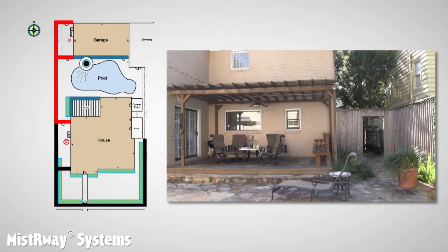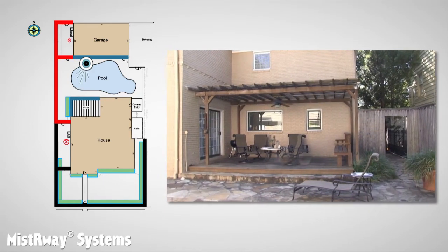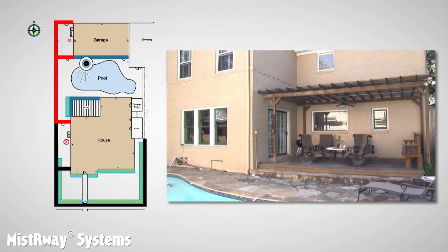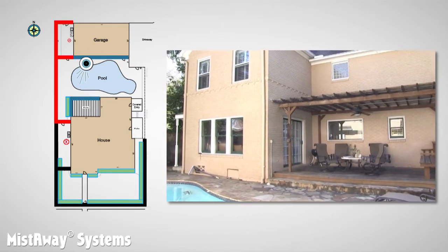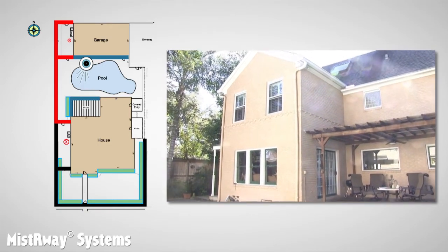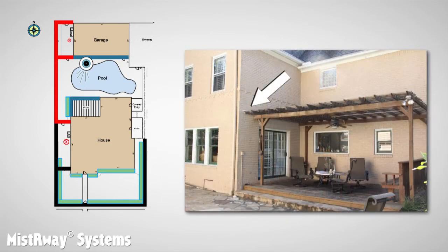We're standing now on the north side of the pool, facing south and panning left to the west. We see the brick wall of the back of the house, which faces north. It is 2 stories here. The eave is way too tall to install nozzles, and we can't put nozzles at ground level because it's all flagstone. So the run that we plan on the eave of the deck will have to terminate at the house.